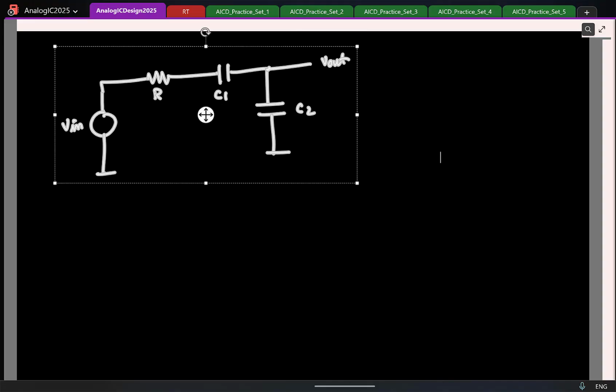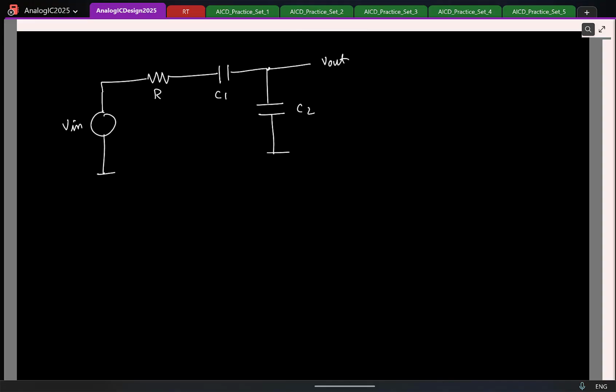Now let's try to find the number of poles and zeros here. Again, remember, the number of poles is the maximum number of capacitor voltages you can initialize in the circuit. For the pole location, the input doesn't matter, so I can assume that Vin is 0. Okay. So how many capacitor voltages can I define independently here? I can define voltage across this fellow and this fellow, no issues. So number of poles is how much? 2 poles.